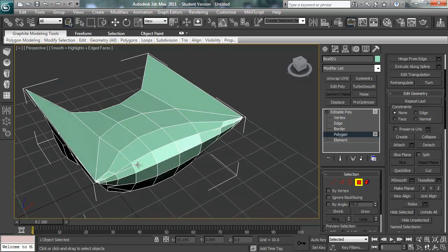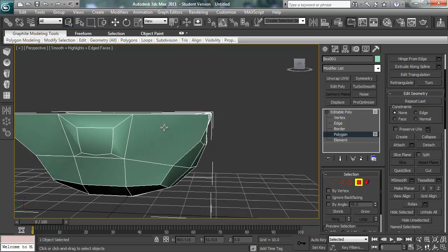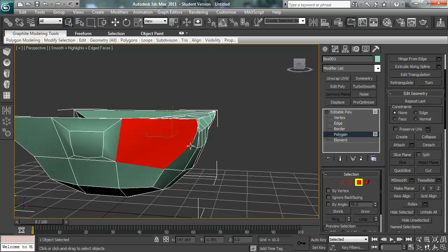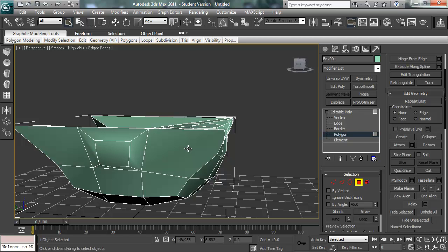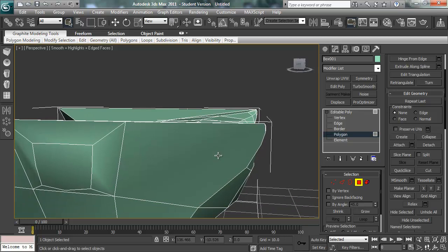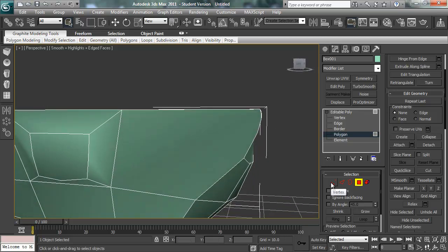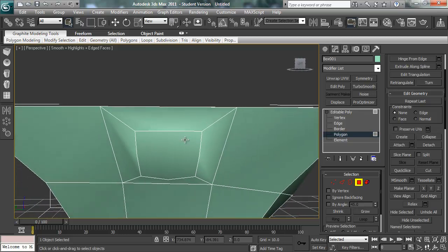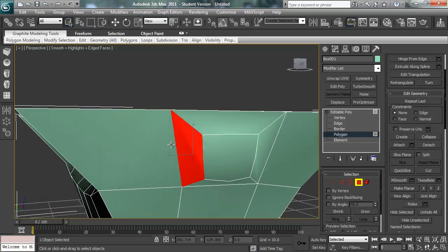At this point we've got, here we go, some polygons which have more than 4 sides. We call those n-gons, is the sort of term we use. And quite often you might want to fix those, but let's say we just want to retriangulate them because they're not going the right direction. This one's a better example actually.